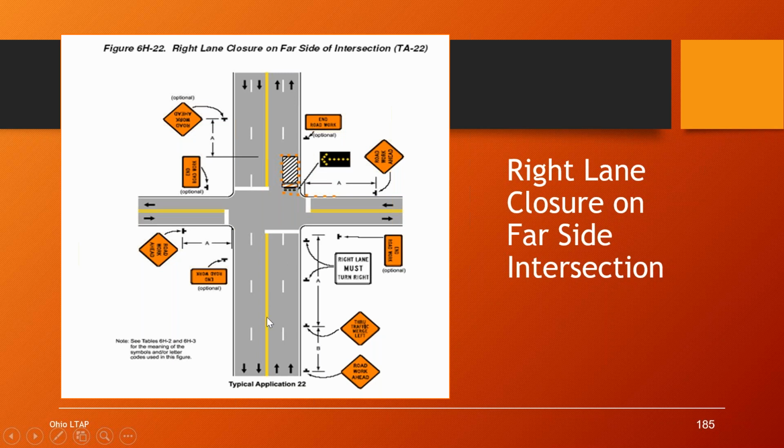And so there's another way to handle this by creating a right turn pocket with cones before this. And you might need to have different signage to do that. So when we talk more about intersections, we'll see that there's some more thought that you can put into this to make things safer and more efficient, depending on the particular traffic volumes and turning movement volumes at each intersection you're working at. So that's the thing we get into when talking about intersections.